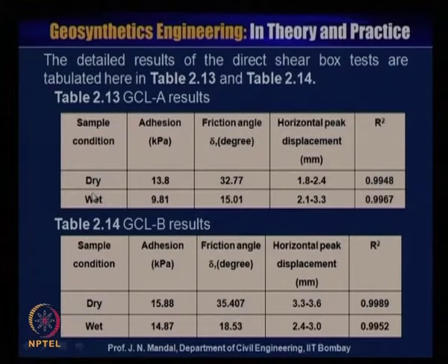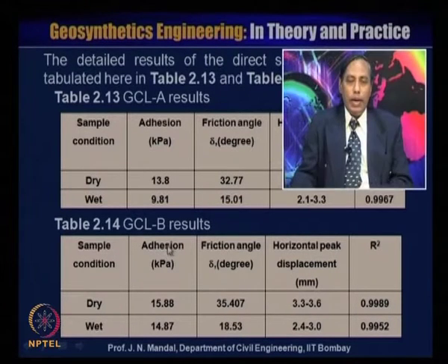You can see that when it is the dry condition, the adhesion and the friction angle are more compared to the wet condition, and the horizontal displacement does not show a significant difference whether the sample is in dry condition or wet condition. Now, this is for the geosynthetic clay liner B.